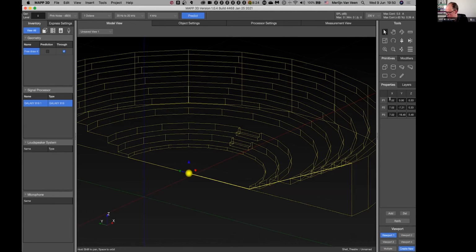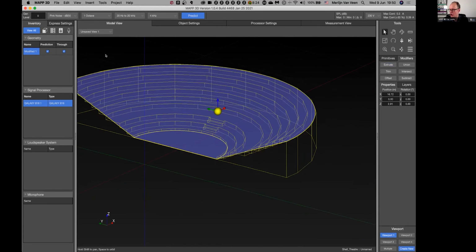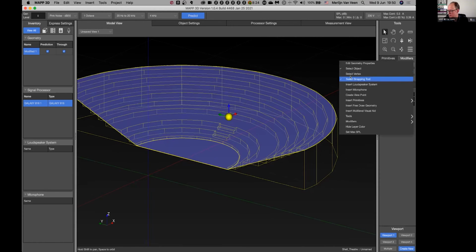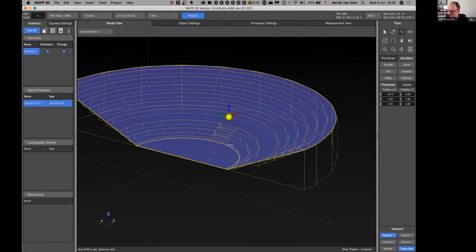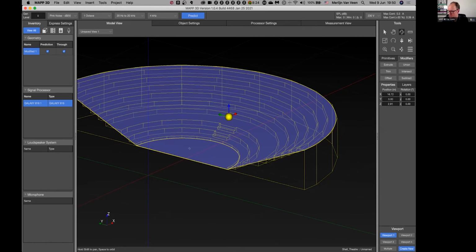And what I can now do is take note of that first point where my gizmo lives, which has an X and a Y value of 702 and 0. Because now I can do another extrusion, an angular extrusion that is, of 180 degrees around the XY coordinates of that first vertex. And if I do that, apply, then lo and behold, within a matter of seconds, I now have an audience plane that nicely tracks the geometry of my imported SketchUp drawing. So that's where your snapping tool comes into the equation.